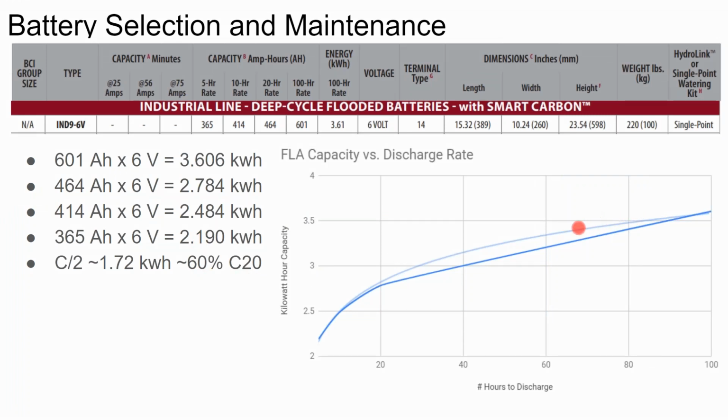What we can see is that lead acid has this logarithmic decay curve that really starts hitting once you get to a C20. And then a C10 would be here, and then a C5 would be here. Then by the time you get to a C2, pretty much everything coming out of that lead acid is going to be heat. And so you just don't use lead acid for loads that are 2 hours or less.